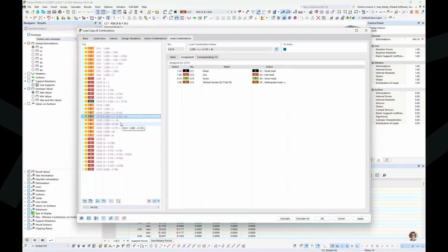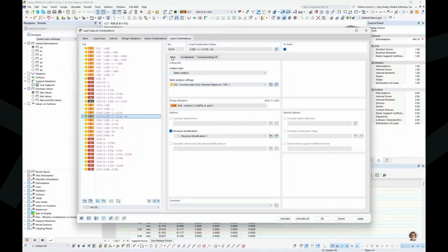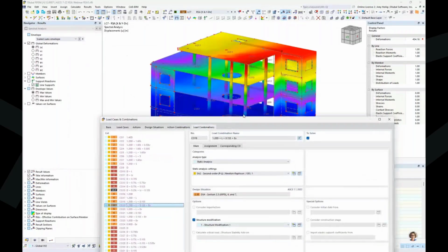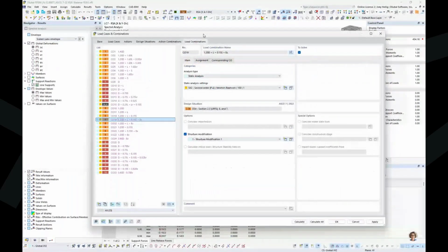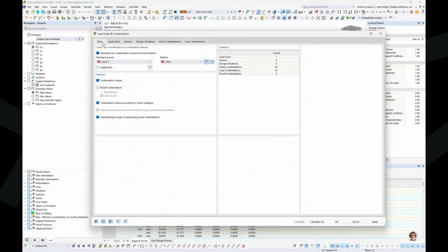And the problem here is that with load combinations, we are going to take all of the loads at once and then run the calculation. And this is what allows us to take into consideration second order effects like P delta, or even third order effects if we had cables or fabric membranes. Well, if you remember from our response spectrum analysis, we already have the results available to us. So instead, in order to combine these with the other load cases, we have to do this linearly, according to first order analysis, through what we call our result combinations instead.